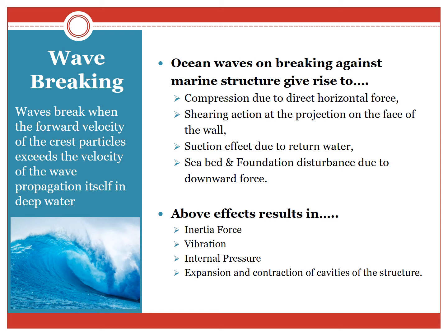It is normally the case when you stand at the ocean beach and the wave hits you, you tend to have a shear action and projection on your feet. But once the water goes back, that is the suction effect that is created. So that effect is known as the suction effect. Lastly, the seabed and the foundation disturbance due to the downward force of the collapse of the wave.